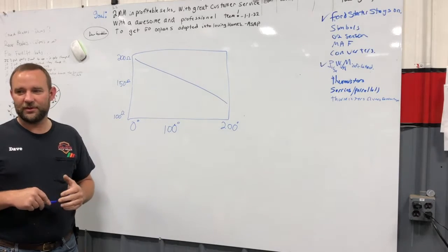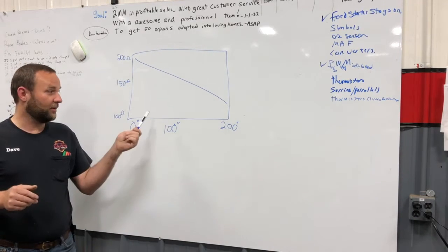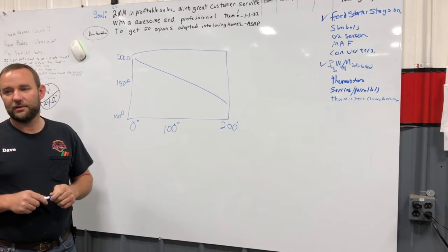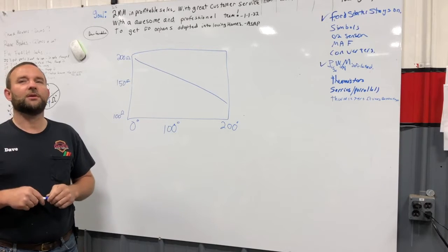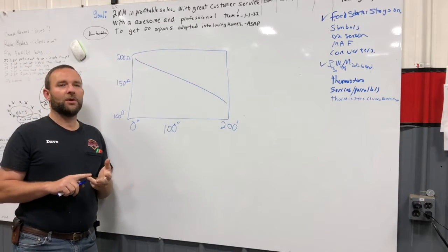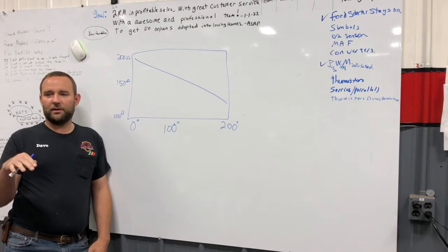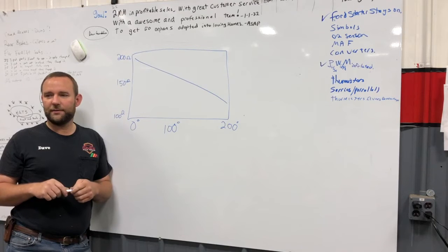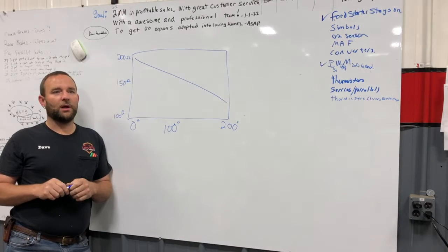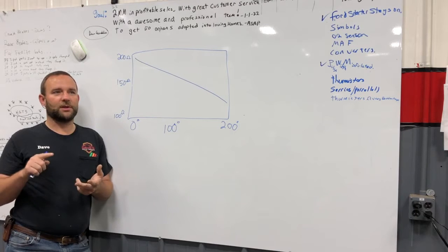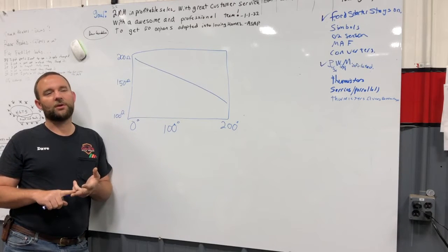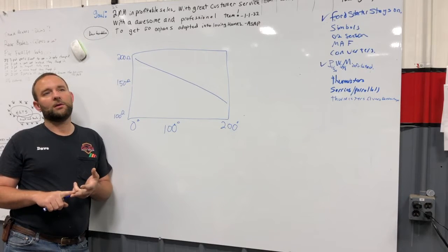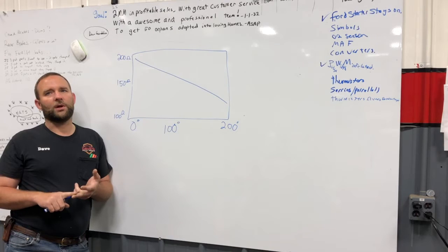How does it know what temperature it is? Oh yeah. Thermistor. It's underneath the front of the car. Ambient air temp sensor. The ambient air temp sensor is a thermistor. So on a car, you have the ambient air temp sensor. You have thermistors inside. How does your heater and control module, if it has automatic temperature control, know where to put it and stay? Thermistors. Intake air temp sensor and coolant temp sensor are the critical ones for fuel injection. I'm trying to think how many more there are on a car. Not a lot.